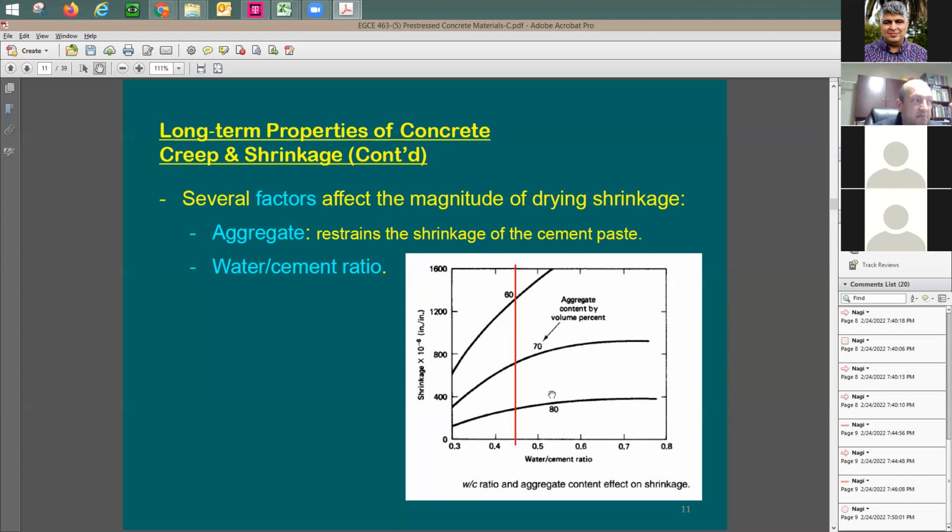So we can say this is going to be very important, right? Your concrete mix is designed for pre-stress. So yeah, now it's going to be critical. I need to pick the appropriate mix design for my work. I'd like to add as much aggregate as I can. At the same time, I'm also looking for higher strength, meaning I need to look at the mix design and pick the one that has a high aggregate portion or percentage. At the same time, I'm looking for a certain strength. This is going to be tricky here. I need to balance my choice.